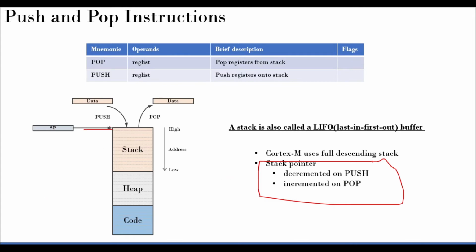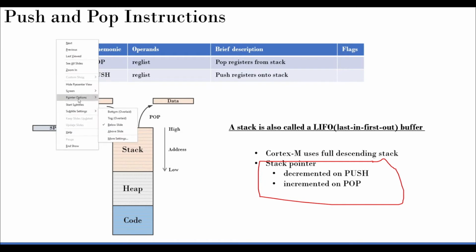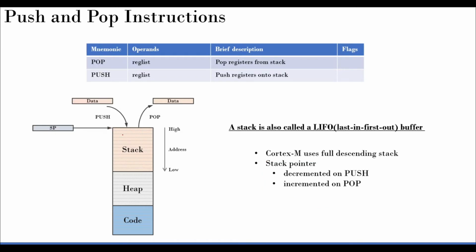Okay, so let's say you fill this position, then you go to the next, but the address is actually going from high to low. So that's the concept. Keep that always in mind. Whenever you are doing the push operation to the stack, that means you are adding memory to the stack, you are going to decrement the address, not increment the address. That is because the stack is growing upside down, not the normal way.